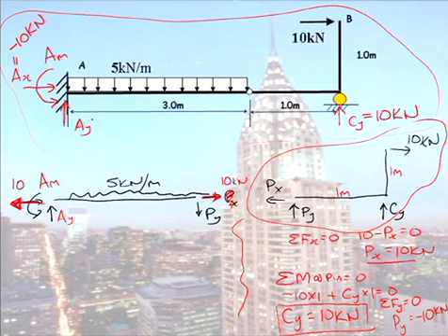So you could solve for AY and solve for AM. But what I will do is I will move to my left-hand side free body diagram. We said PY, this force here, is actually a downward force of 10. So therefore, that means this force here, when we move across, is an upwards force of 10 kilonewtons. Can everyone see that? And I'll scribble that out. So now I have my unknown pin forces as known values, and I treat them as if they are now loads applied.